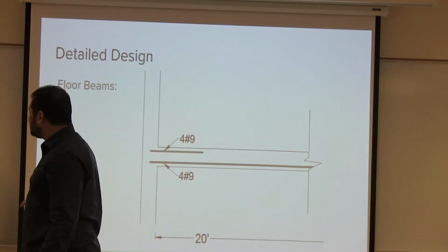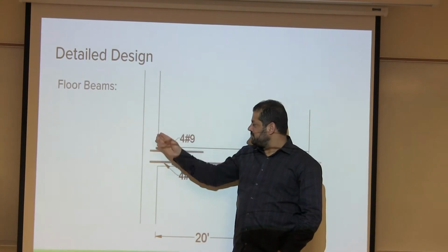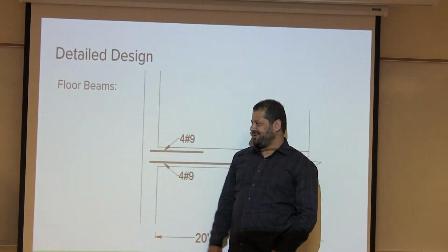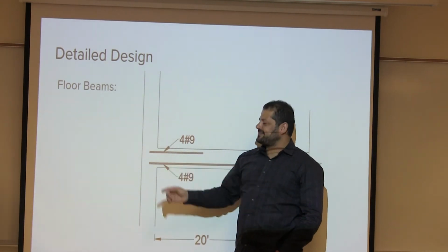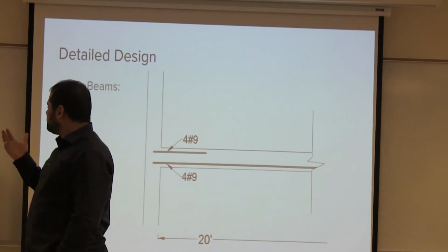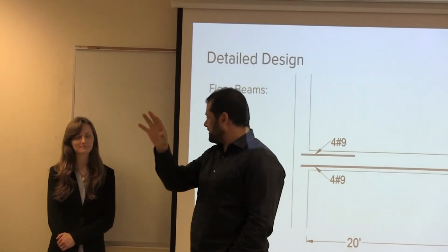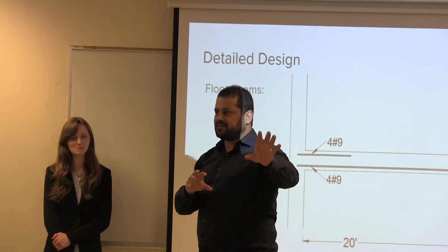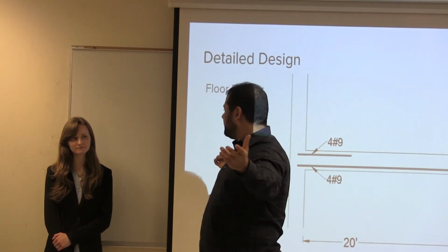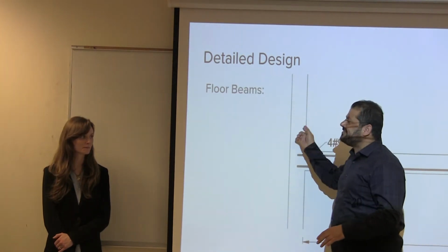No, unless you fix it. So why did you get that moment at the beginning then? Because you assigned it as a fix in your modeling. Yes, your detailing doesn't show a fix. You can ask the software to do anything you want. This is the dangerous thing. I mean, you design it as a fix, your guy details it as a pin, and you go with the cracking. So if you design it as a fix, you want to make sure your reinforcement provides fixation.